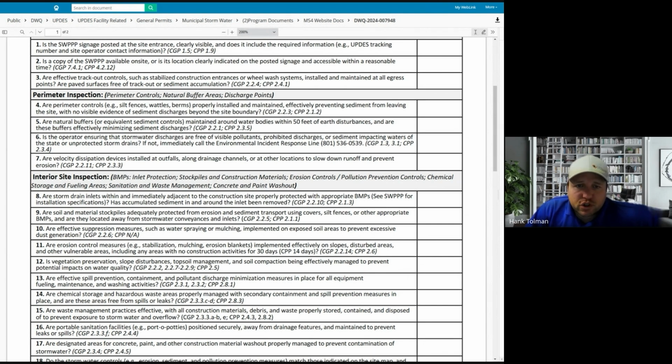Sometimes you might have to install a perimeter control upslope of a disturbance, right? Let's say you have a big hillside that has been graded out. I was talking to Bruce and Doug the other day, and we were talking about potentially putting straw wattle or even silt fence at the top of a grading, atop of where they're going to grade a really steep slope.